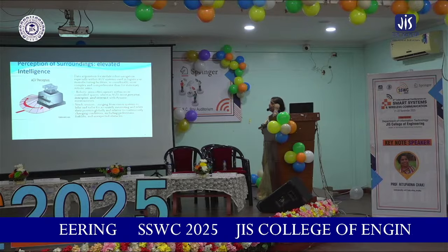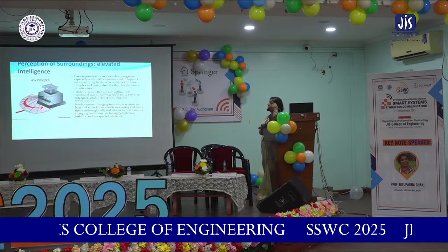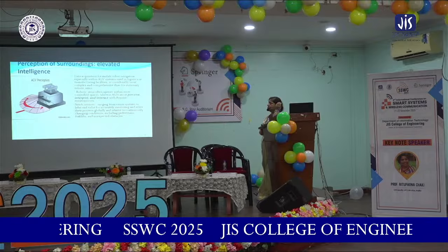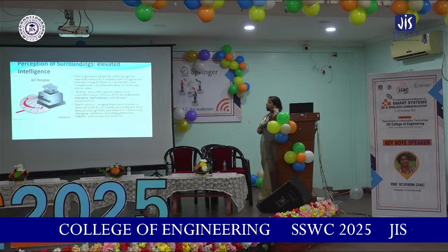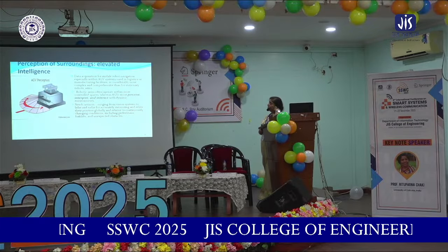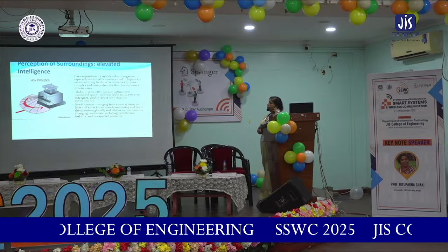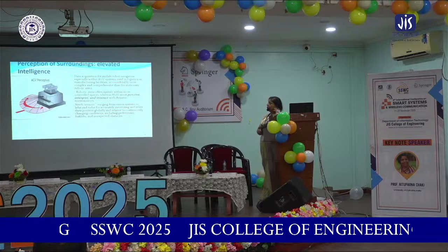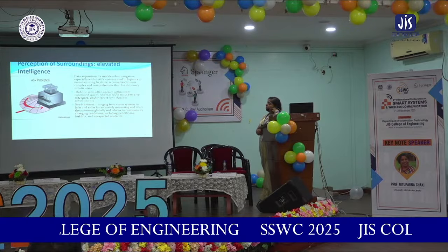So these are some things that need sensors, ranging from vision systems to LIDAR and radar, for accurately measuring their position globally and relative to continuously changing conditions, including when you are moving across hospital corridors or streets. They have to understand how many pedestrians are moving across, whether there are any forklifts and unexpected obstacles. All of these things are to be perceived, and that is actually a very complex task to be performed by the robot.